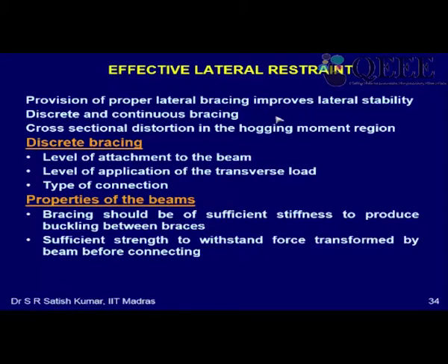So what we do is basically we take L as the original length for lateral buckling, and we find MCR is much less than MP or MY, whatever. So the beam is laterally buckling at very low strength. So I want to increase the strength. So first I'll give one support at the middle and reduce my effective length to half.